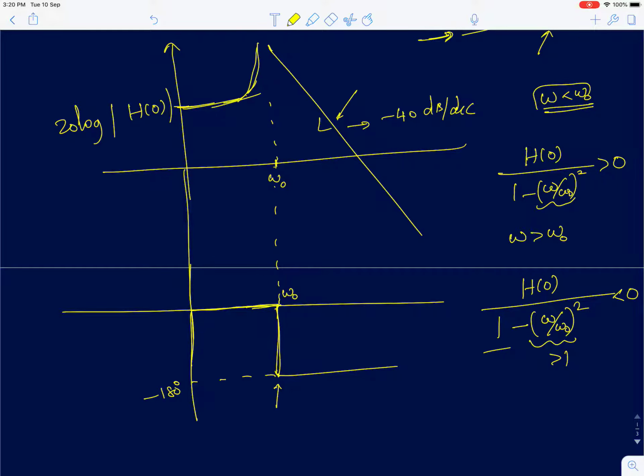In fact, all the filters we have encountered in the previous lectures had a gradual, graceful transition in phase. For a single pole system, it could go from 0 to minus 90. For a system with a zero, on the right or left of the plane, it would go from 0 to plus 90. The shift was always graceful, following an inverse tangent function. But here, it was actually a sudden change in the phase at omega equal to omega naught.